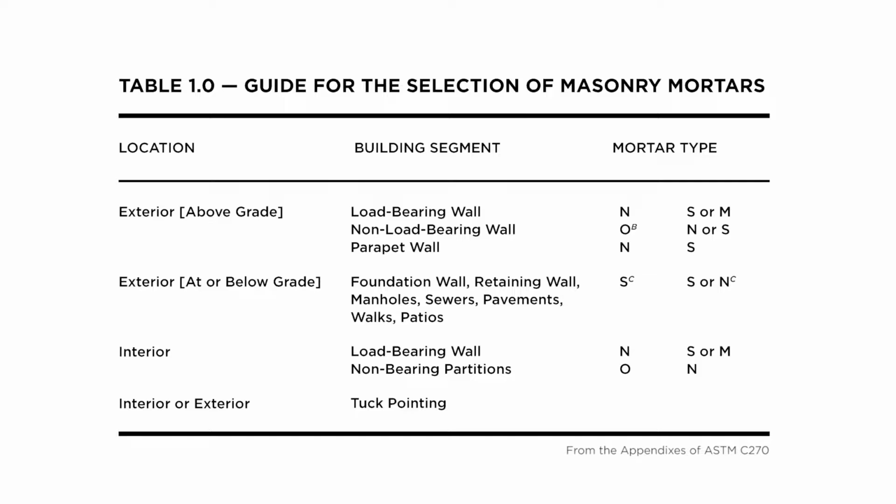Listed below is a very basic guide for architects and engineers on the selection of mortar that has been adopted from ASTM C270, Standard Specification for Mortar for Unit Masonry. Understanding typical uses can help avoid job site errors of using the wrong mortar type at certain locations. It is common for multiple types of mortar to be used on the same job. Plans and specifications must list the type of mortar to be used in various locations of the structure.